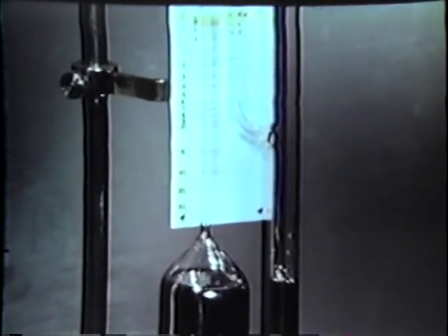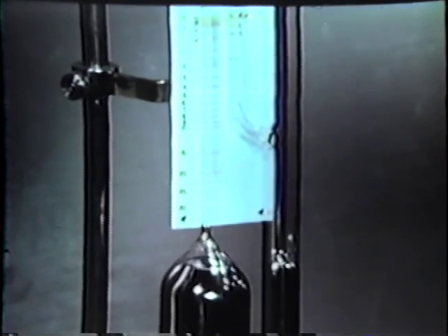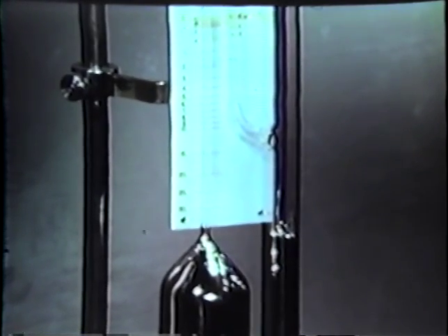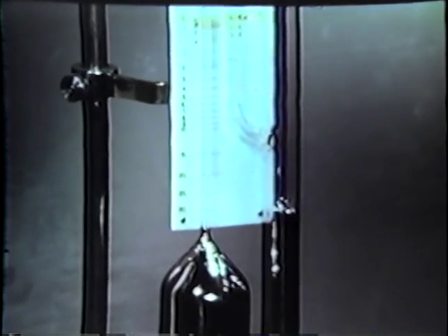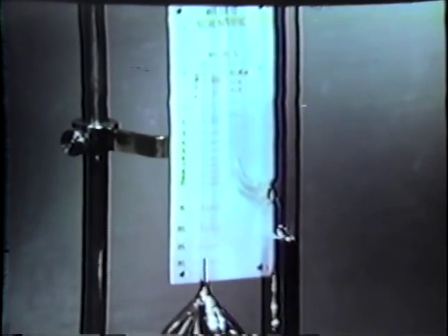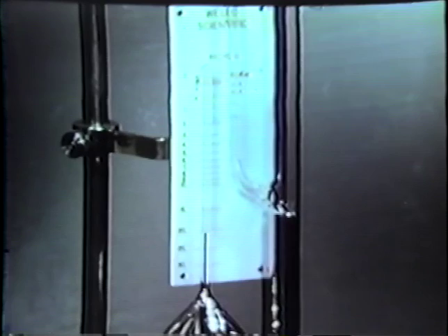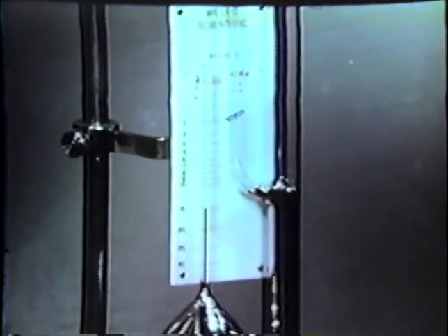In addition, the rising mercury will compress water vapor in the sealed capillary, condense it, and thus remove it from the sample. The McLeod gauge, therefore, does not indicate the pressure of vapor that may have been present in the sample. The advantage of the McLeod gauge is that it is the least variable of all gauges, since its reading depends on the physical dimensions of the tubing and the bulb, and these can be calculated and controlled.